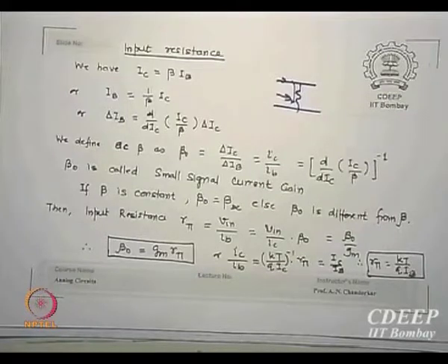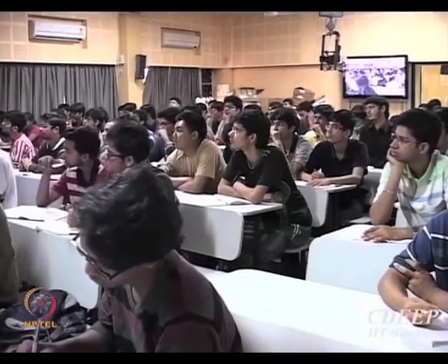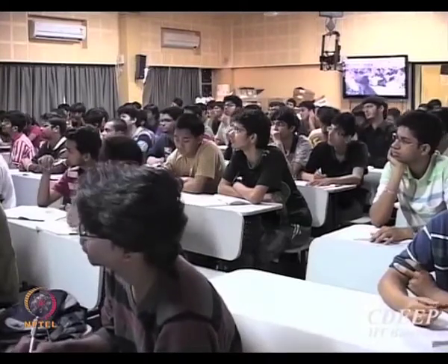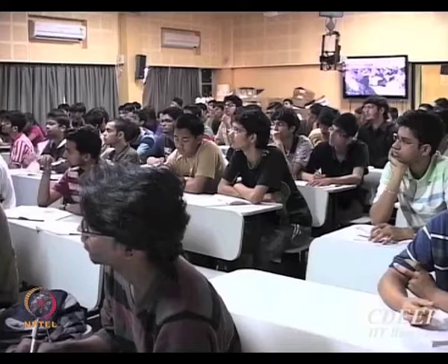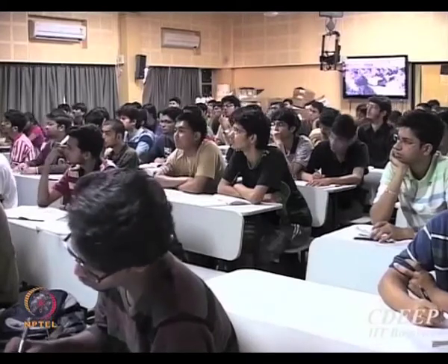So in your design or in your circuit, you must ensure, if you are using the same values of beta, that beta is constant. Why can beta change? Can you tell me? You have done devices now. Beta can change because of two things. Base width is correct, but I am looking from external. You are right, base width is major because that's the beta factor. Directly it will decide alpha T. Okay. Temperature, you are very good.